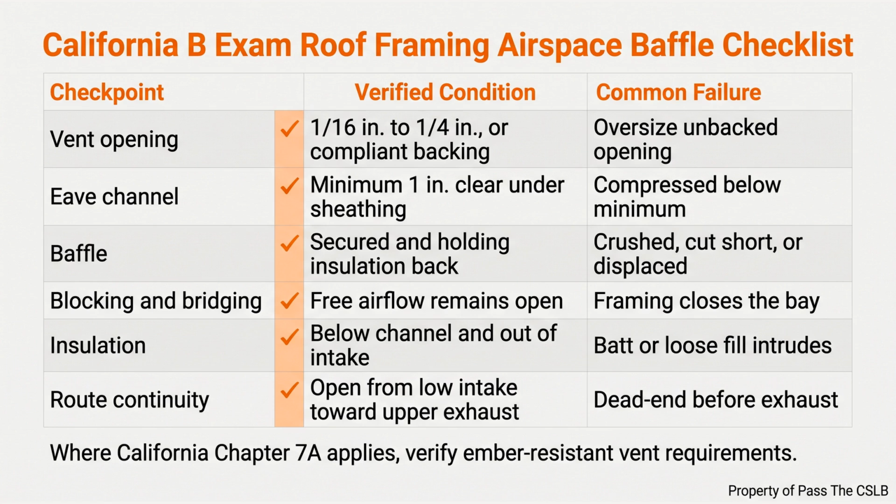The same principle applies in a vaulted ceiling where drywall follows the underside of rafters. Each enclosed rafter space needs its intended ventilation path unless the approved design uses a compliant unvented assembly. Stuffing insulation tightly against the deck and hoping the ridge vent handles the rest does not preserve an airway.